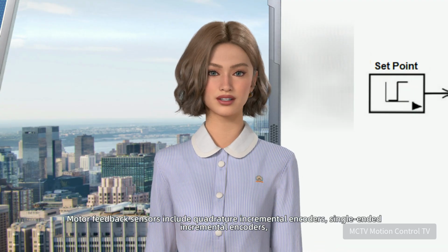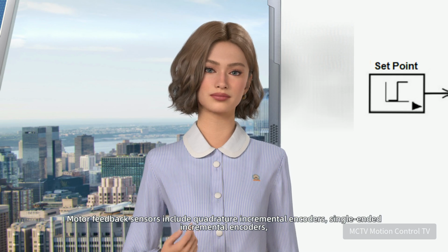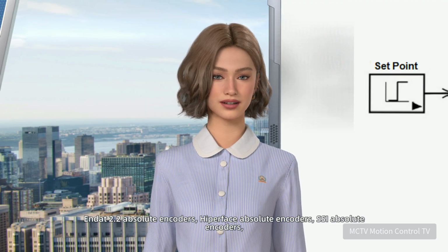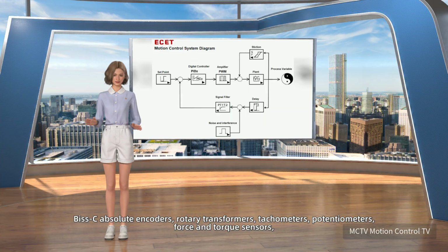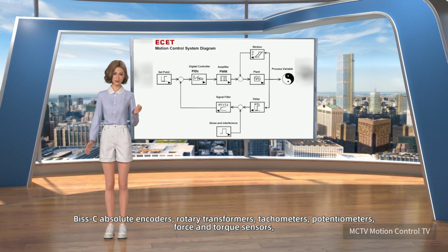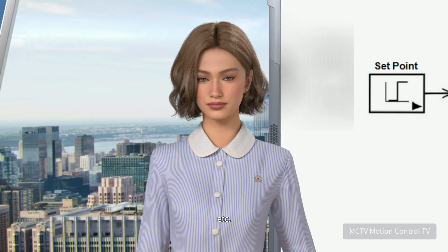Motor feedback sensors include quadrature incremental encoders, single-ended incremental encoders, absolute encoders, hyperphase absolute encoders, SSI absolute encoders, BiSS absolute encoders, rotary transformers, tachometers, potentiometers, force and torque sensors, etc.